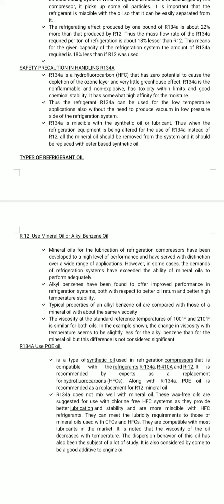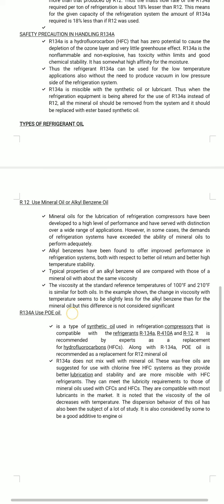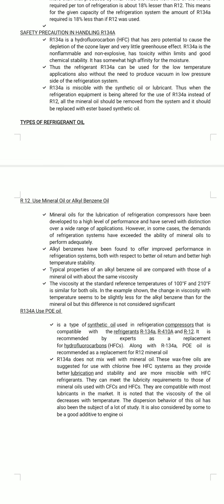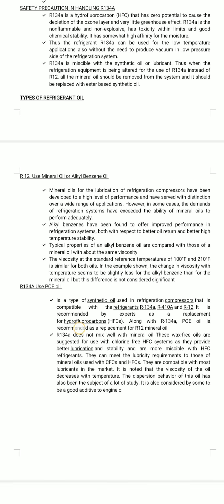134A is a hydrofluorocarbon or HFC that has zero potential to cause the depletion of the ozone layer and very little greenhouse effect. R134A is non-flammable and non-explosive, has toxicity within limits and good chemical stability. It has somewhat high affinity for the moisture.